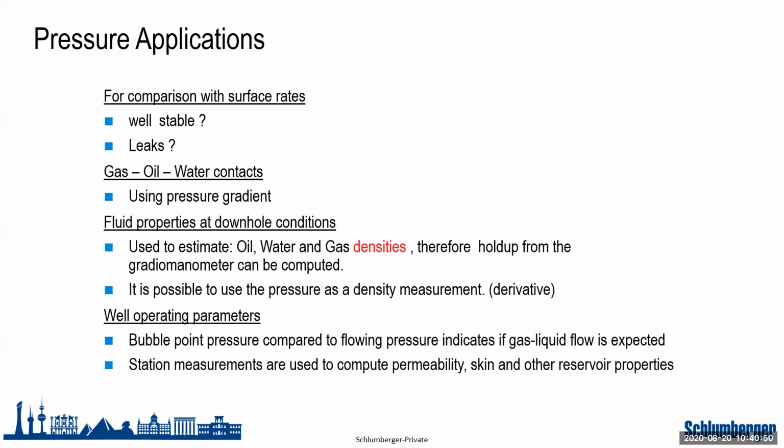And also we can understand some well operating parameters, like we can do production logging for testing. In this case, we can understand bubble point pressure, and we can derive some factors such as permeability and skin. Okay, so we can do what we call multi-layer testing with production logging, which is an advanced type of application from production logging.